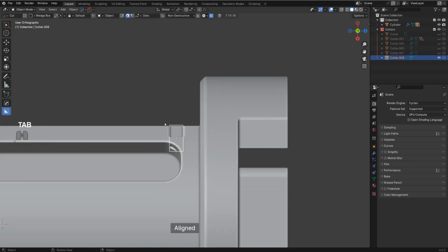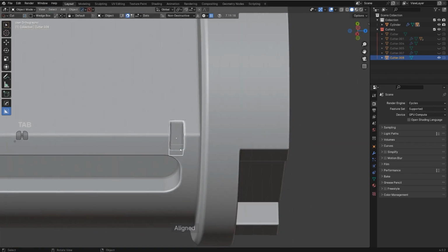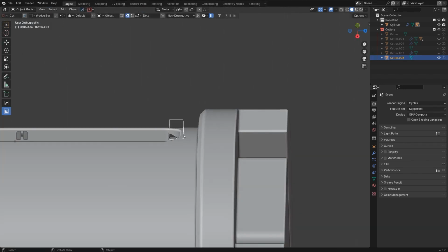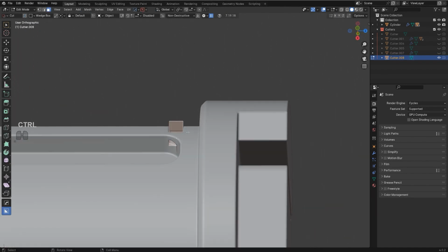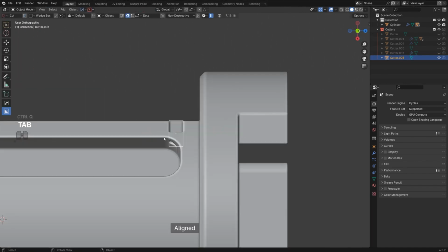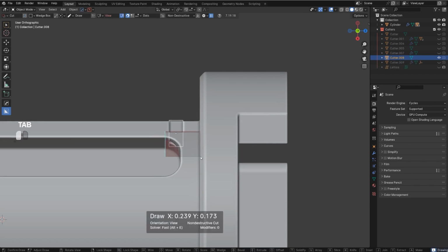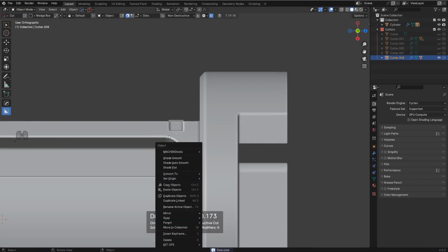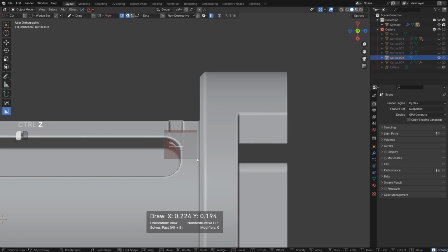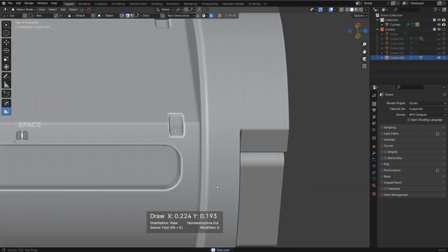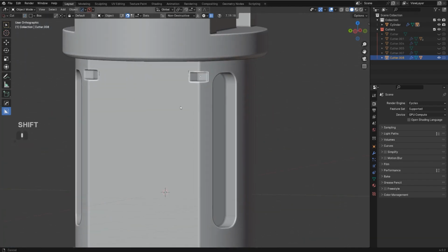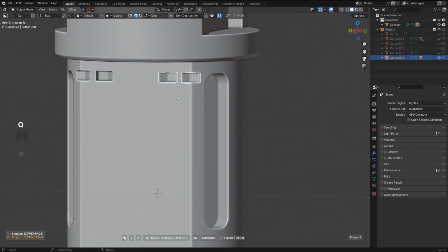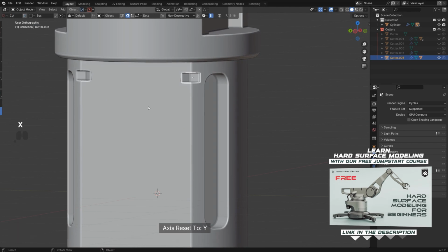And click, and then we're going to cut it. So we need to cut this bit here, right? You see that? So one more time, Control Q and click, and then we're going to cut it like this. No, one more time. Press W to turn off the wedge cut and cut it like that. And we're going to get this nice cut in the corner. This is what I want. And then we're going to array this down. So X and where is it?